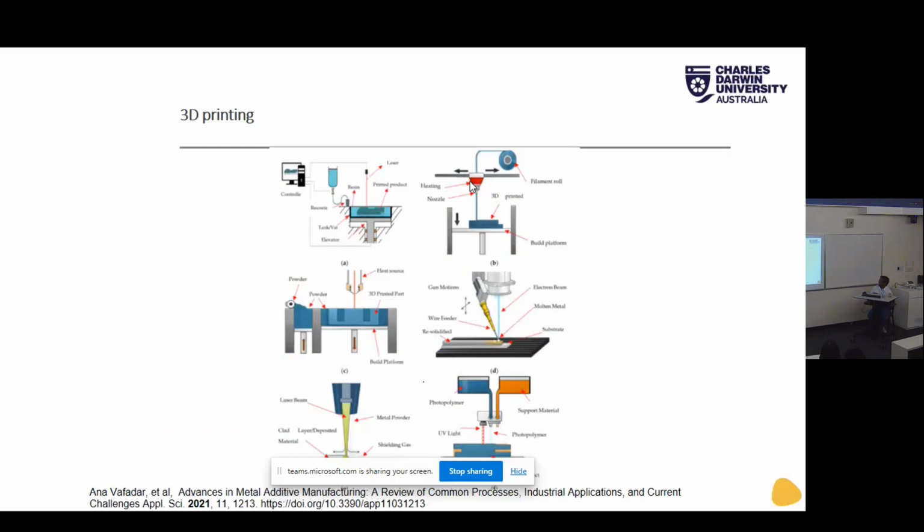And in all of this, the heat source will keep moving as it is dictated by the shape of the product. The layer size would be dictated by how fine you want the form to be, and how much processing needs to be done at a later stage. And then the infill is another matter, which will dictate the strength of the part.